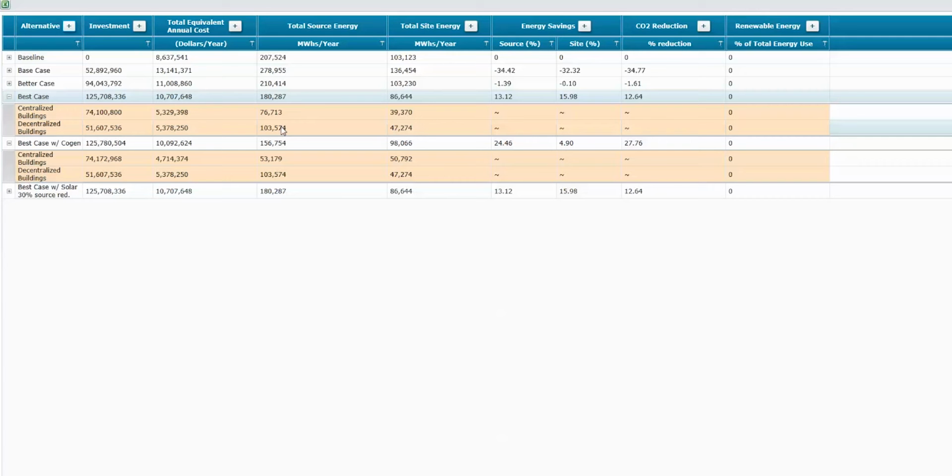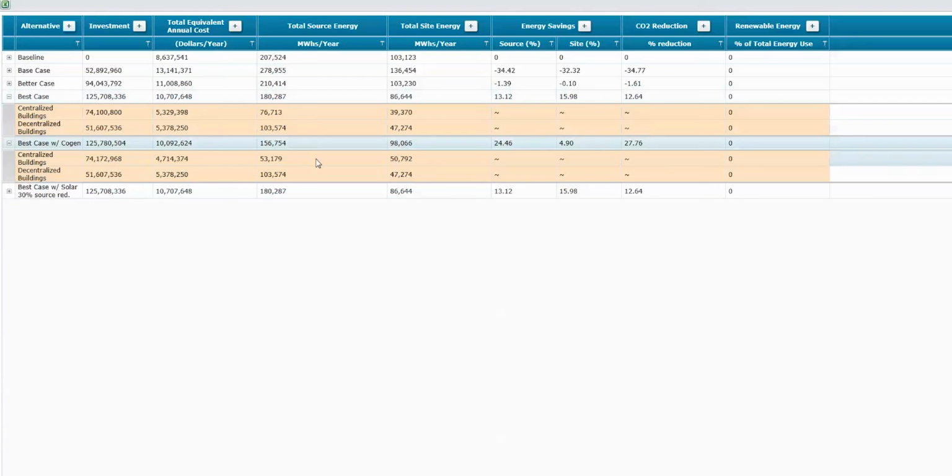But we don't have that in this situation. We don't have a chilled water network or anything in this study. So here, the differences are primarily just due to the buildings, the size of them, and the loads for the types of buildings that are included. When you move on, though, to the cogen solution, now we see a real benefit to having these buildings grouped together, to having that synergy that can come from having a reciprocating engine and waste heat recovery.